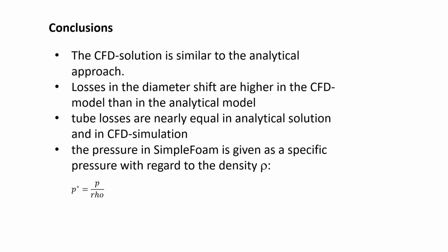Okay, let's come to the conclusion. The CFD solution is similar to the analytical approach. The losses in the diameter shift are higher in the CFD model than in the analytical model. Tube losses are nearly equal in analytical solutions and in CFD simulation. And what you must always pay attention to is that if you look at the pressure in simpleFoam, the pressure is given as a specific pressure with regard to the density rho. Meaning we have a P asterisk, which is the pressure divided by the density.